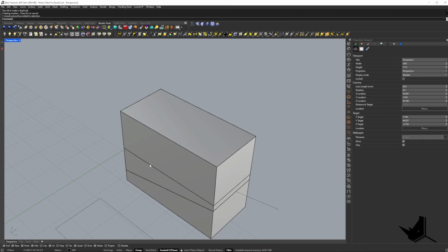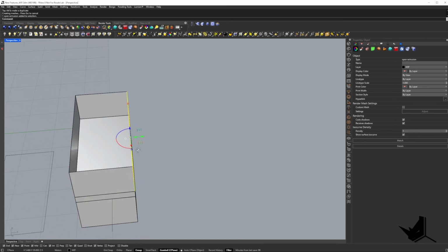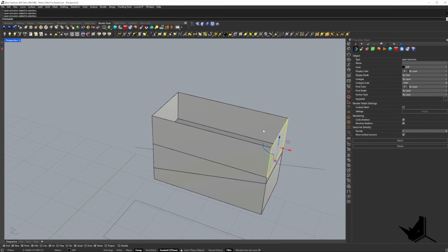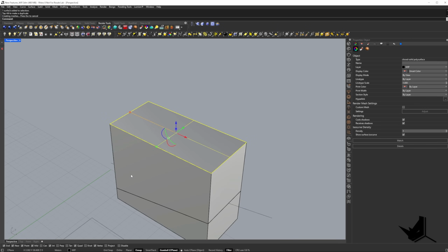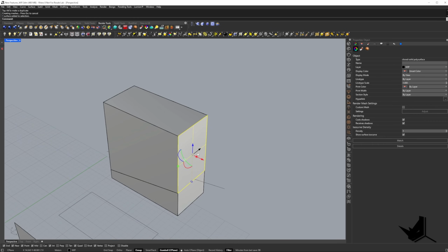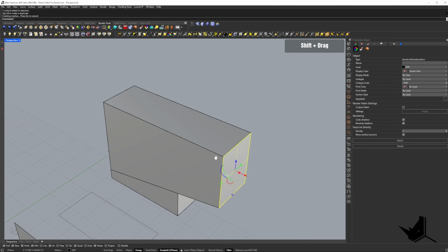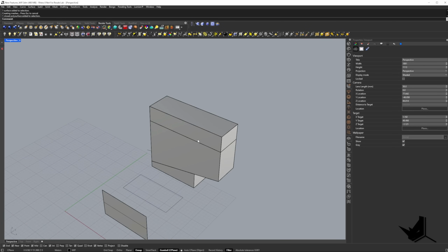When I press Control Z, let's do it again. This time let's hold Control. When I hold Control, you'll see that I get something like this. I have individual faces extruded. All right. And then after that, we have extend face. When you hold Shift, this just moves everything together like this, so it's extending the face. So we can select the face, and hold Shift to extend the face. And then of course you have numeric entry, which means that you simply click here and type, let's say 5, and you get the same extrusion on the top.